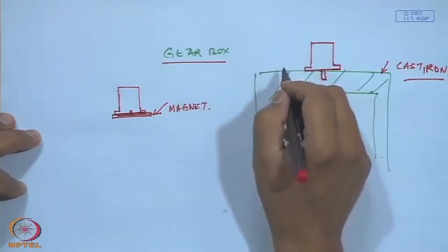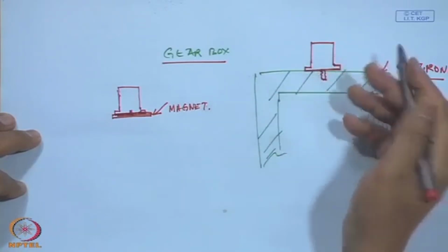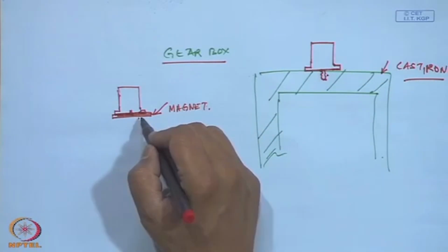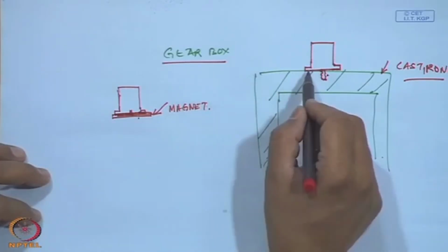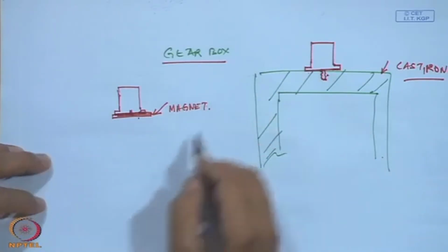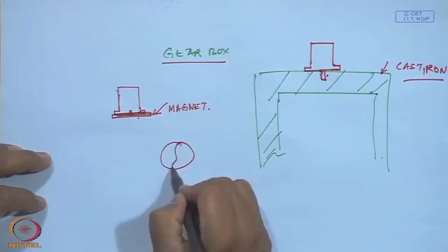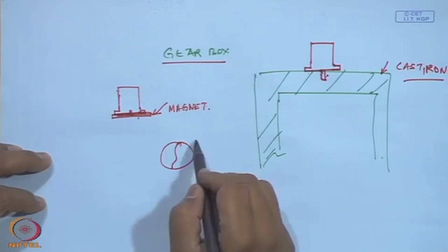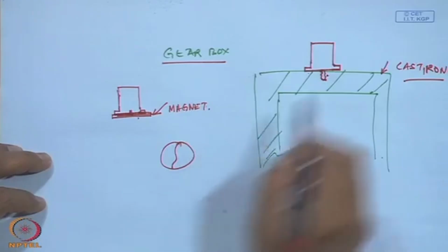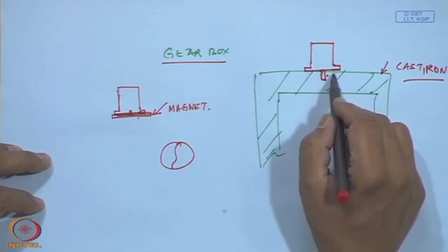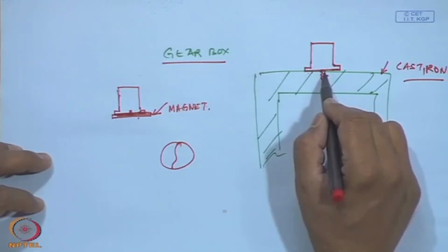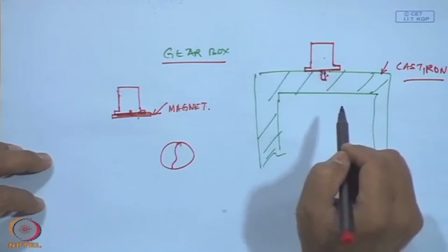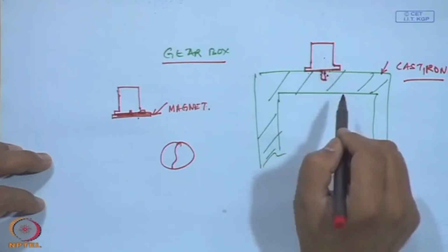Okay. But again, out of my experience I am telling you, these soft magnets are very soft. These magnets cannot be subjected to high temperatures. With time suddenly you will see that the magnet has cracked. So, usually these magnets cannot withstand high temperatures. So, usually if you have to mount permanently, you make a hole and put a stud, and then you screw the accelerometer onto it.